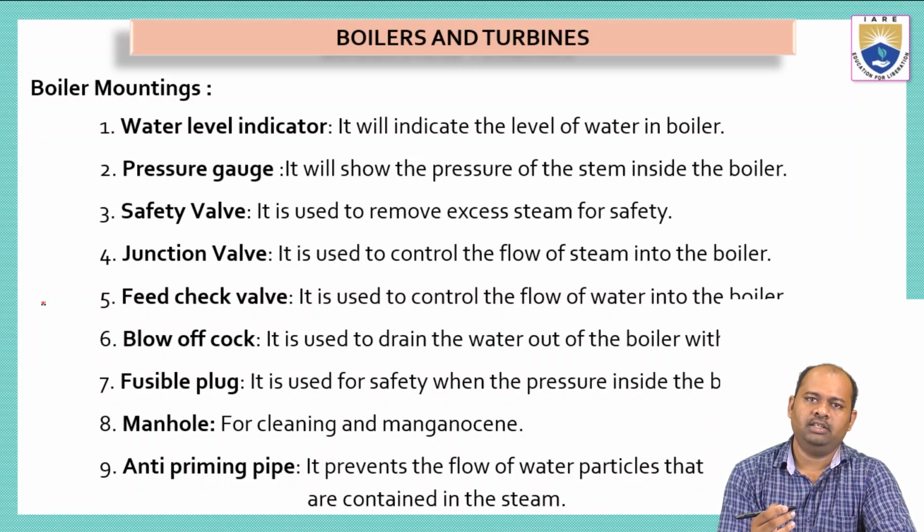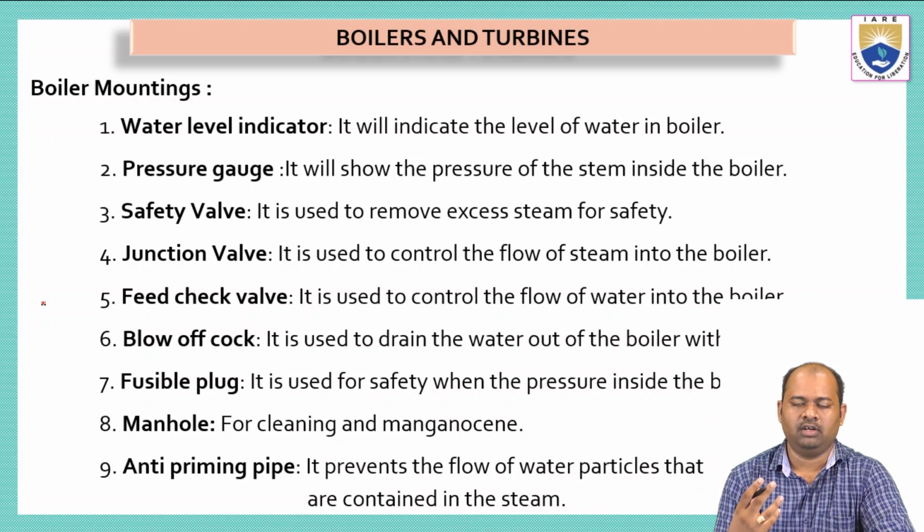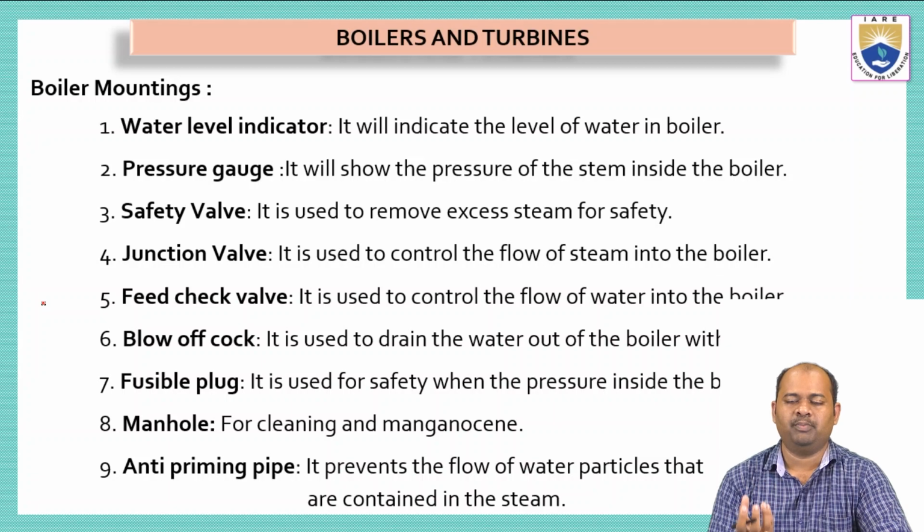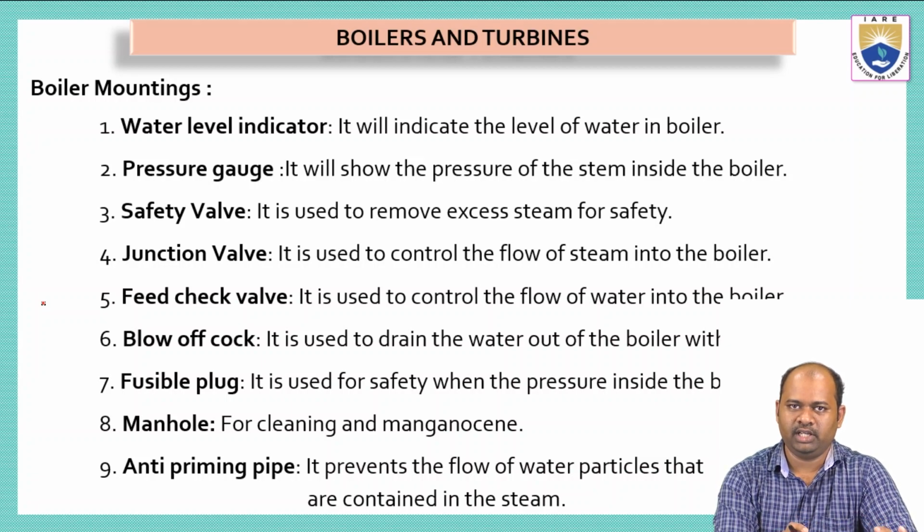So generally any boiler will have an area where water is taken, because ultimately we have to produce steam, for which the raw product is water. So in order to produce steam, we have to use water. This water has to be taken into a tank which is closed, obviously, because we have to close the tank in order to supply heat. Otherwise the steam will be escaping into the atmosphere. There is no use of heating the water. So whenever we take water and heat it, the formation of steam will be seen. So we have to take this water in a closed container or a tank.